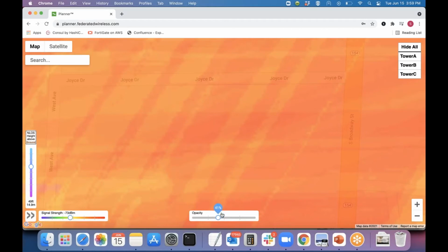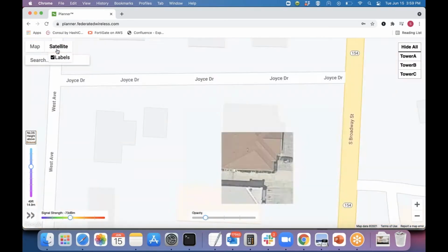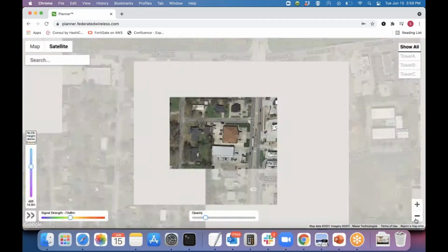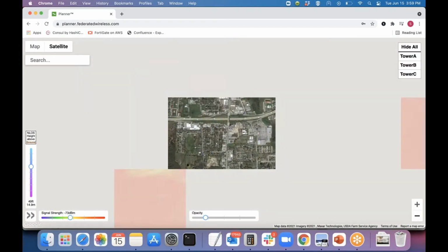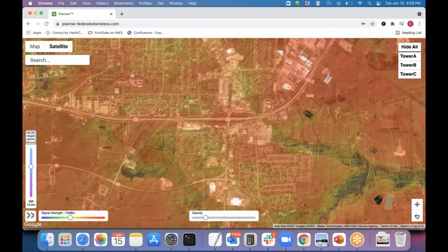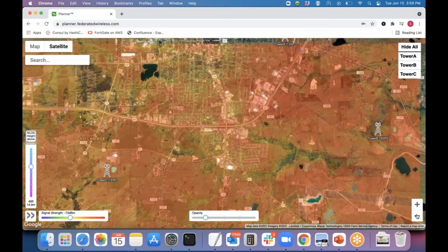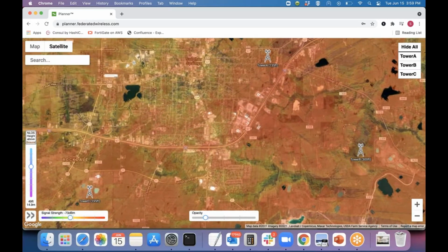When it gets to using the tool to get the access points added, I'll just zoom out so we can see all the three base stations. So if you wanted to add a fourth base station in your network view, the customer will have to just provide all the information related to the fourth base station, in terms of antenna height, location, max transmission power, and other details.